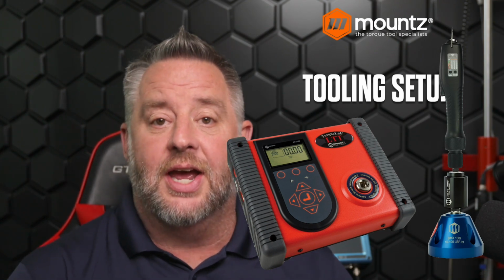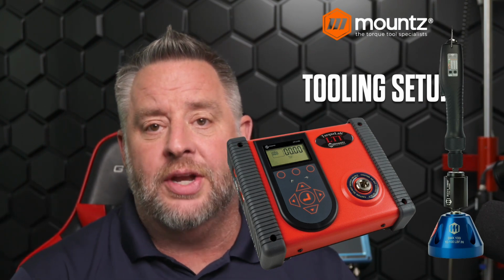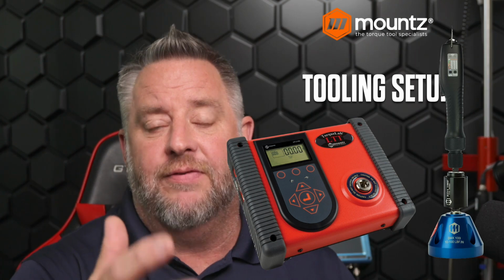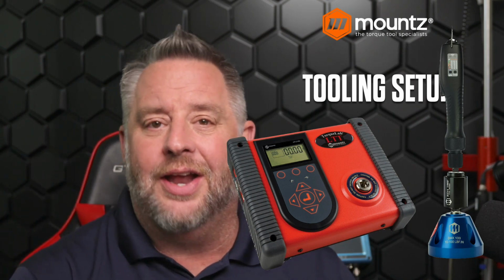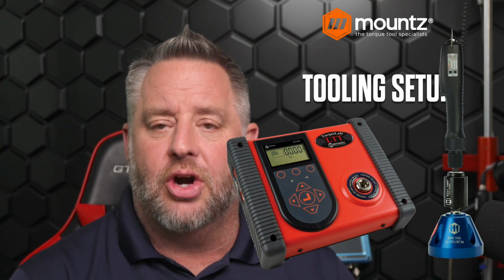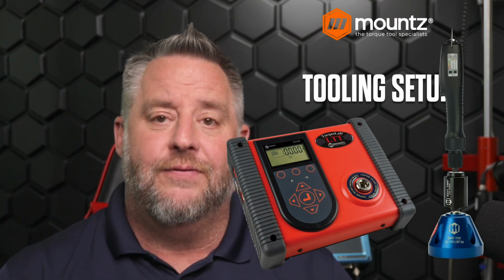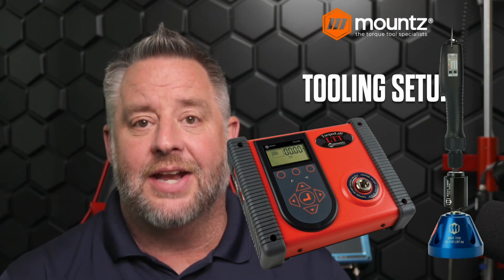And this can be used again to test a hand tool, either on the internal or the external sensor, and also then setting up an electric tool with the use of a rundown adapter or a joint simulator for that tool. Because when we're doing an electric tool, we want to make sure that the tool gets up to its RPM speed and then shuts off, because the inertia that happens when a tool shuts off is part of the torque delivery. And so we want to make sure that we're using a rundown adapter for an electric tool during that setup period.